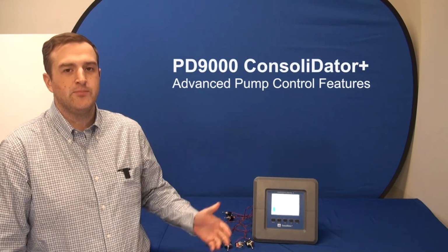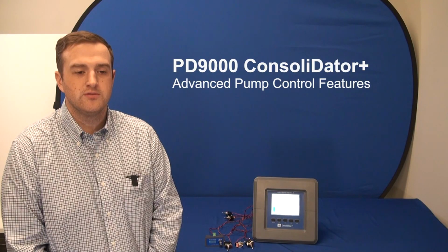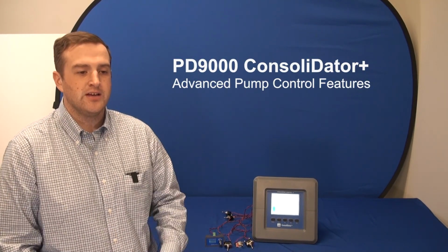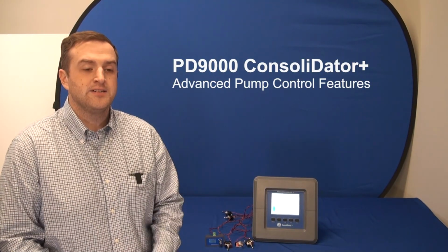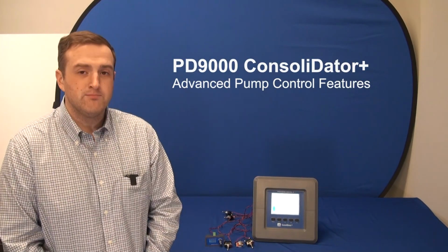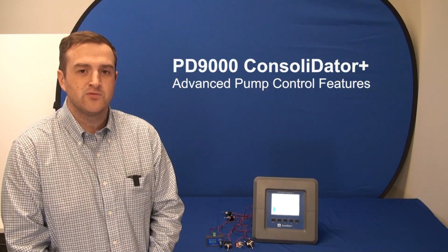Today we're looking at a PD9000 multivariable controller set up for some of the new advanced pump control features. We're looking at a pump down pump station where we have a continuous level sensor, 3 floats, and a couple of digital inputs for alarms. The station is set up to do pump alternation, alternating between 2 pumps, with some lead lag capabilities as well.